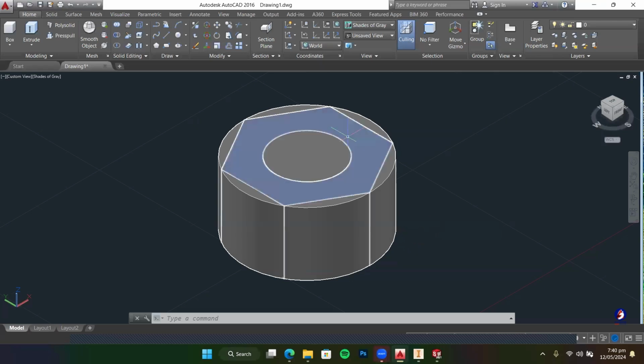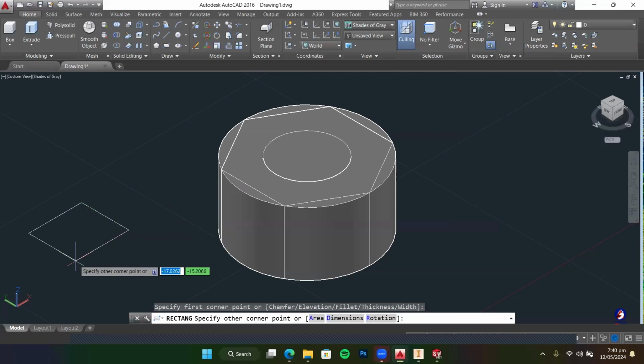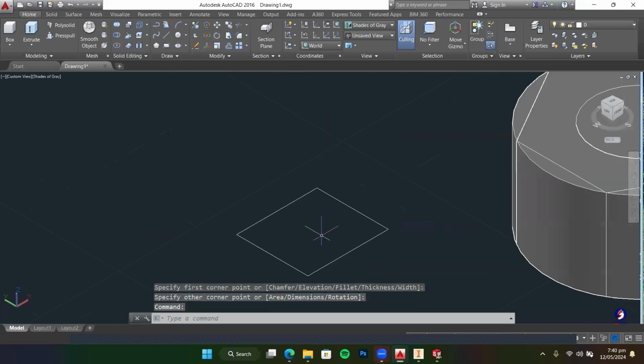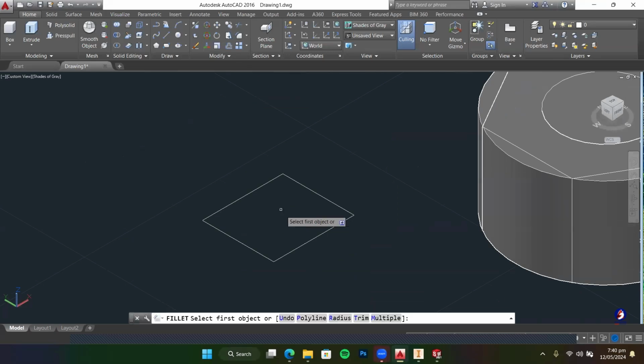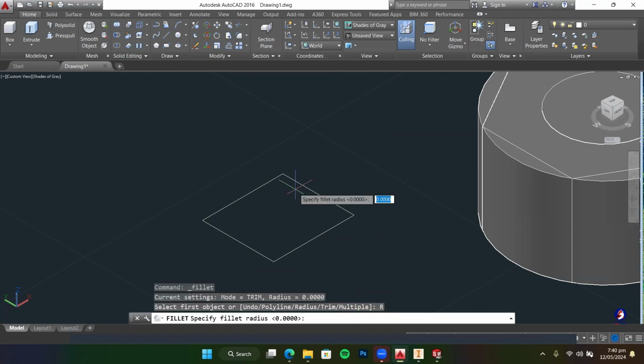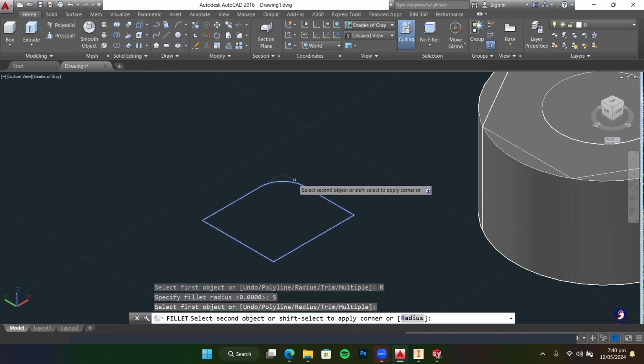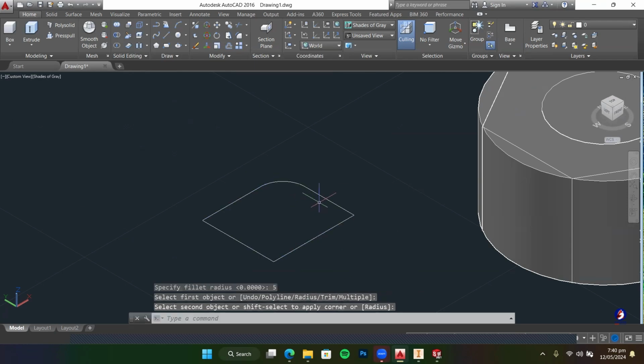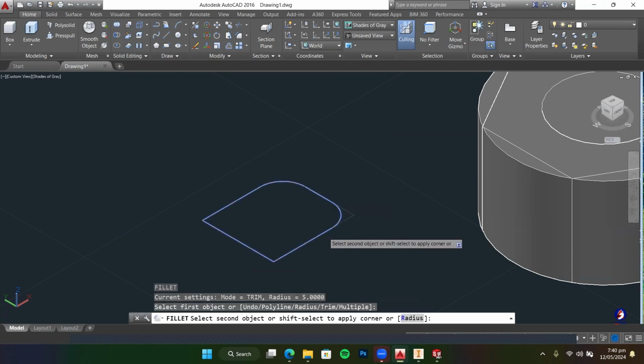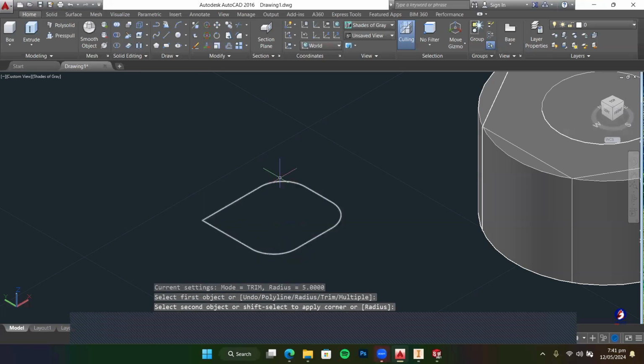I think I talked about this too, the first day we did this meeting. Let me draw a small box over here. I talked about the filleting tool, right? You select this side, you select your fillet tool over here. Select the radius you want to fillet. As I want to fillet 5, select my 5. You see it has been curved, right? The corners have been curved with a filleting tool.